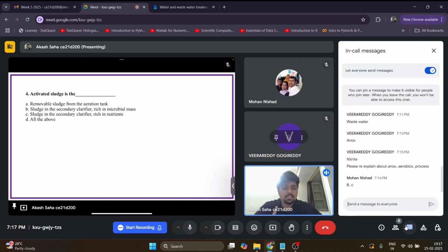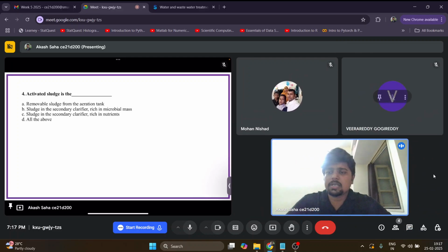And as far as this question is concerned, okay, you are answering B and C. Actually, only one answer is correct. So I know you people may be getting confused whether the sludge is rich in microbial mass or is it rich in nutrients. So mostly if proper denitrification or biological phosphorus removal processes are being done along with the aeration, then the nutrients will be very much lesser.